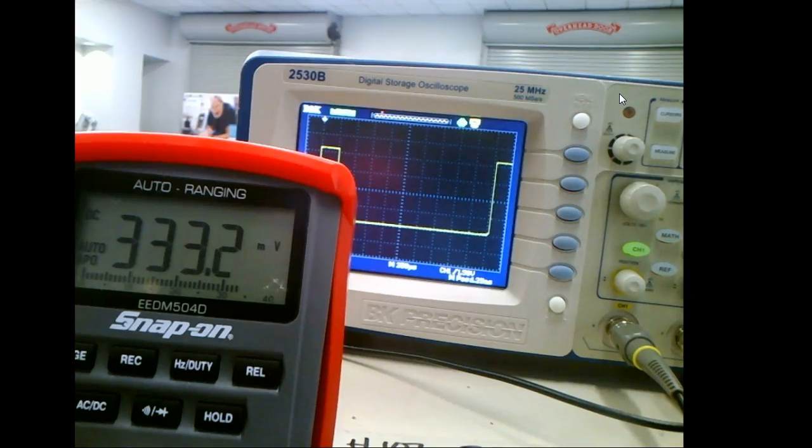Not with pulse width modulation. This is the first time I showed y'all pulse width modulation. We had it, but we controlled it with the output of my power supply. So what we were doing is changing the output of my power supply. Now that would be pretty efficient, but then I couldn't use the same power supply to run my PLC that I run my motors with, right?